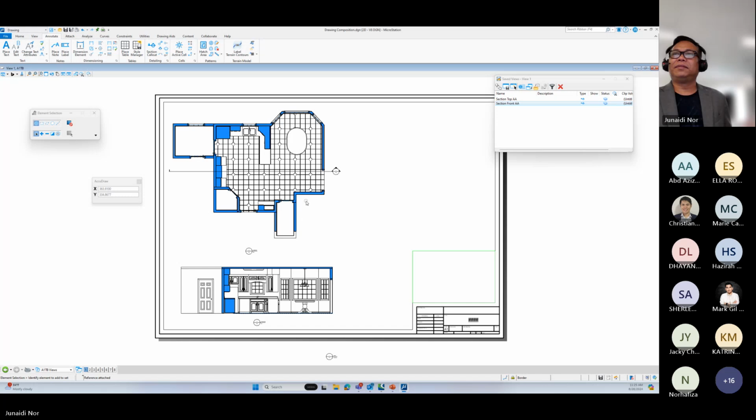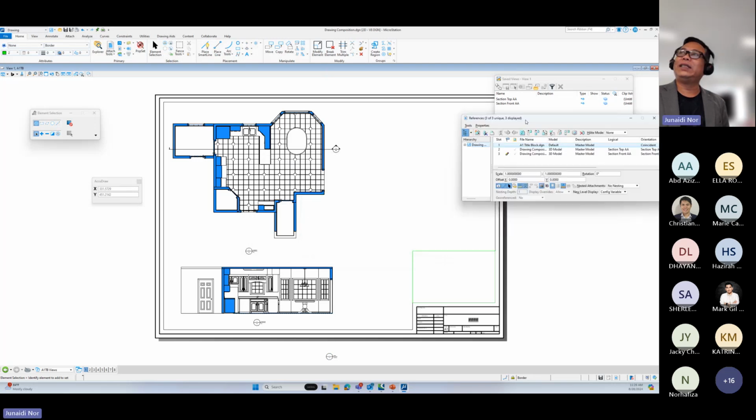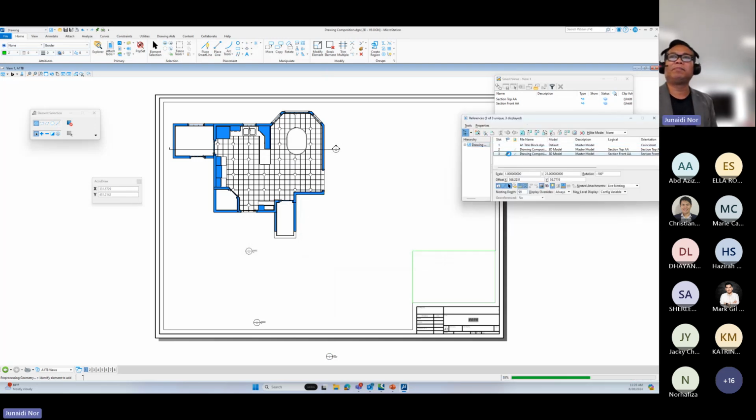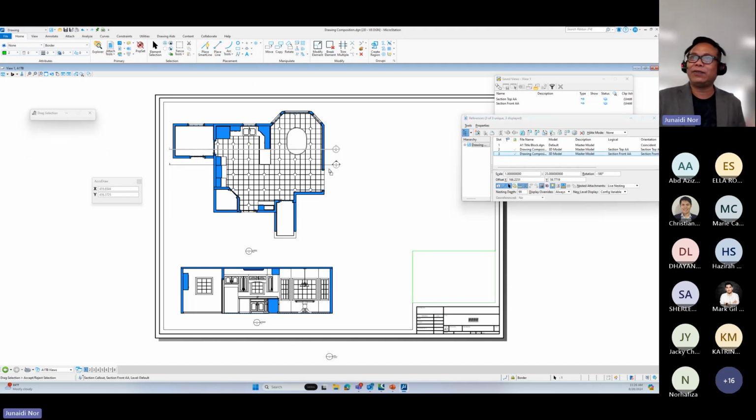See? If let's say you have changed the front view to the inner part, you don't need to cut section again. You just modify from here. Go inside here. Okay, and then at the attach, you can see the pencil here, update. If you cannot see clearly, I can just cut from here to here, easier. Okay, click the pencil.